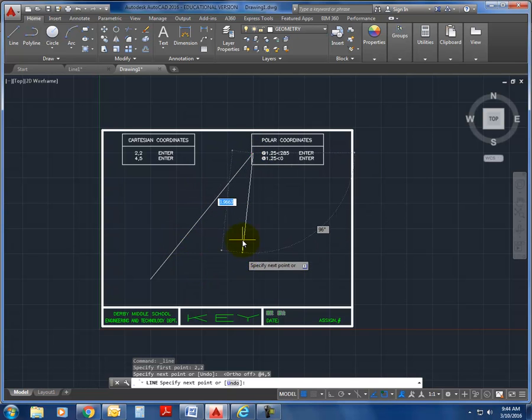Now imagine I want to create a triangle. Well, if I want to create a triangle, I want to move down and none left to right. So let's go 5 down. I want to type in 0, comma, -5.